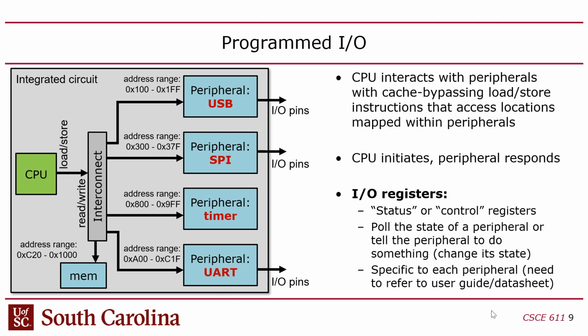So we didn't really talk about the mechanics of how this works. All I said is that in programmed I/O, you assume that there is some kind of read-write interface where you can read an address or write an address, right? I didn't talk about what obviously SPI provides a way to do that, and I2C provides a way to do that. But generally speaking, with a system on chip like this, like I'm showing here, these buses are parallel buses.